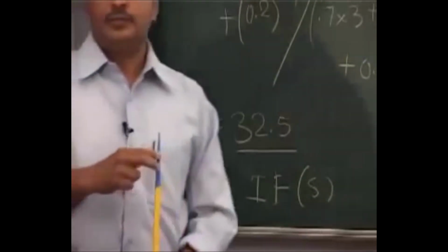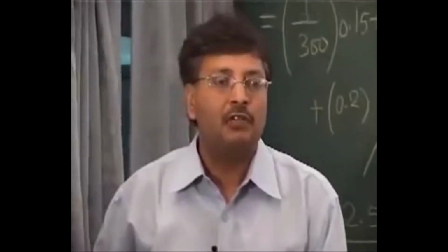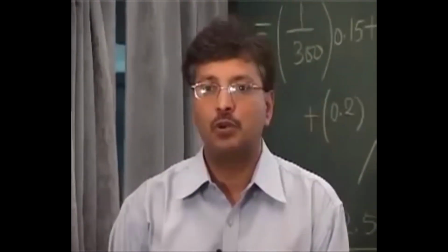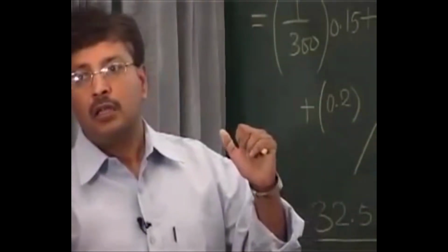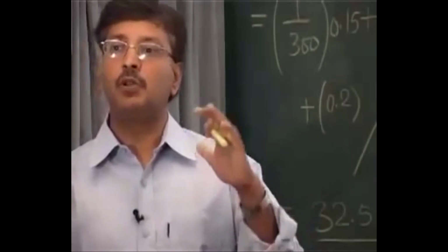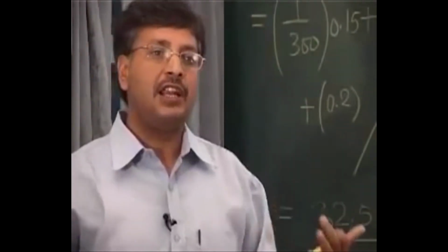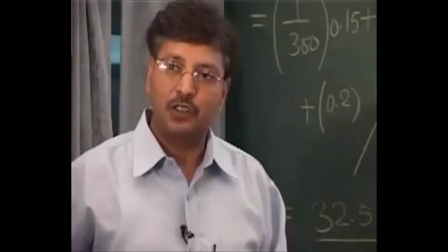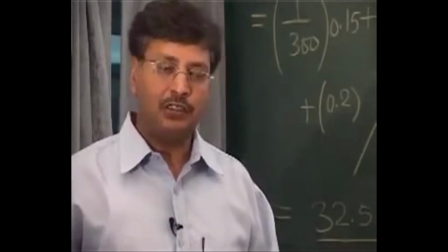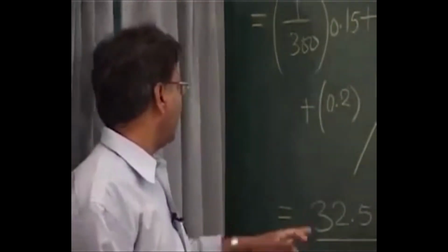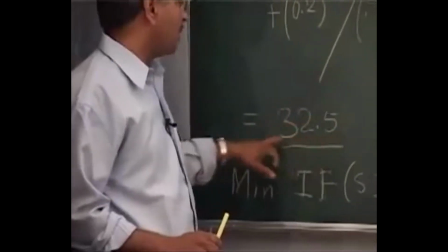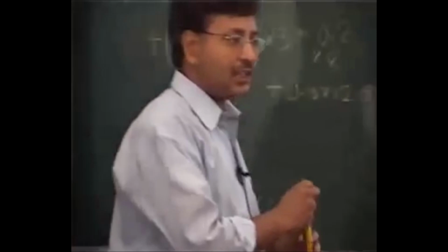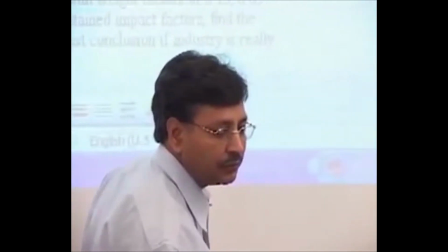If you recall, I said in the class, when you want to find the impact of a source, you look at the downwind direction where the wind is blowing most of the time, and the direction in which wind never blows, which will never have impact. To see the impact of this source, where should I put my station? Because the question asks what should be the two locations.